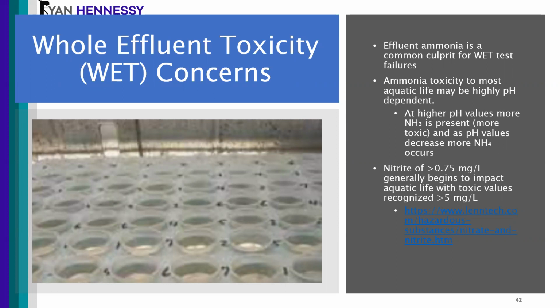Whole effluent toxicity, or your WET testing: ammonia toxicity is very common for WET test failures. At higher pH values, more NH3 is present, which is more toxic. And as the pH values decrease, you get more NH4, which tends to be easier on the Daphnia and the other organisms in that test.